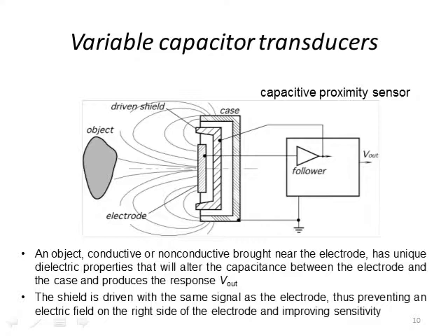And as this proximity sensor, as you change the dielectric in front of the sensor, let's say we have an object. Normally this is in air, so our dielectric function is then equal to 1. Most objects have dielectric constant greater than 1.